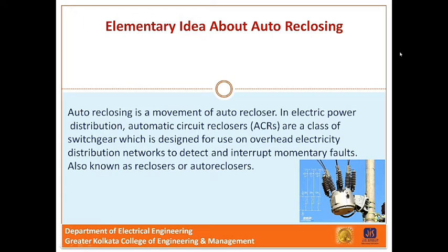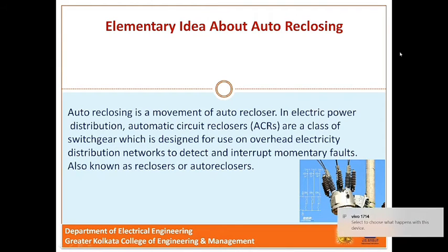Modern automatic circuit reclosers are significantly more advanced than the original hydraulic units. The advent of semiconductor-based electronic protective relays in the 1980s resulted in increased sophistication, allowing for differing responses to the various cases of abnormal operation or a fault on distribution networks. The high voltage insulation and interrupting device in the modern recloser typically consists of a solid-state dielectric insulation with vacuum interrupters for the current interruption and arc quenching.